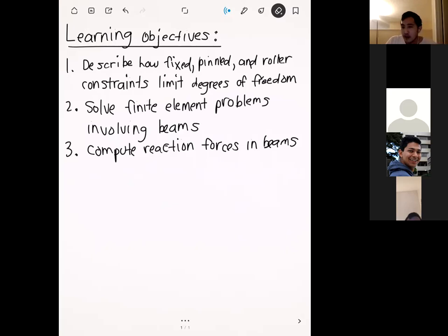Yeah, last year when I taught the class, there were a few people really interested in it because it's a big deal if you're running finite element simulations of 3D printed parts. With 3D printed parts, it's a lot stronger in certain directions, except for the one that you printed it in, because those layers are on top of each other. So if you're doing something like that for your final project, an anisotropic material would be something good to use for that. I have handouts prepared for later in the semester for it.